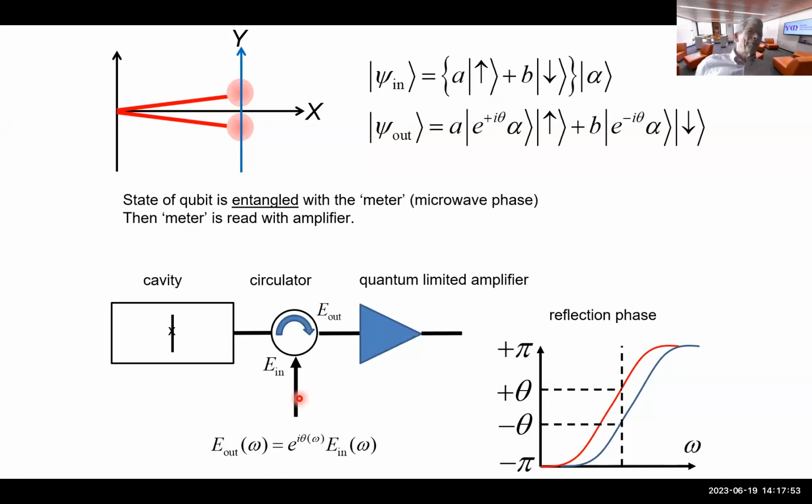On the other hand, if you couple your transmon to a low Q cavity, it may spontaneously radiate out through that. That's the Purcell effect. So you have to do some tricks to put in what are called Purcell filters, or some mechanism that lets you do a fast readout but doesn't give you a corresponding fast decay of the qubit.